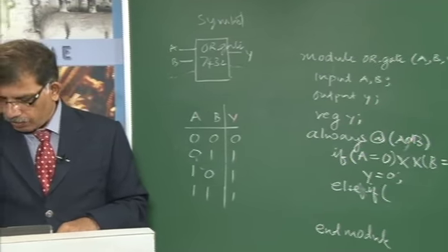combinational logic circuits. In combinational logic circuits, we will be studying Boolean algebra as well as the simplification methods or techniques. What we do in the beginning is discuss the basic laws and De Morgan's theorems in terms of Boolean equations, and then we will simplify simple equations in terms of combinational logic circuits, and then we go for the representation in terms of SOP or POS, and then we will see how to simplify that circuit.